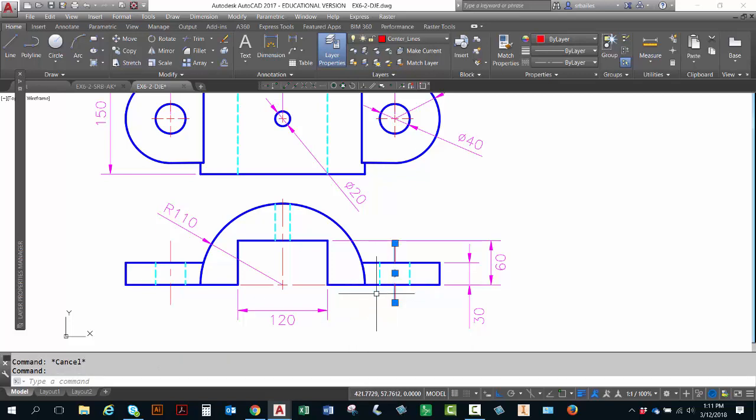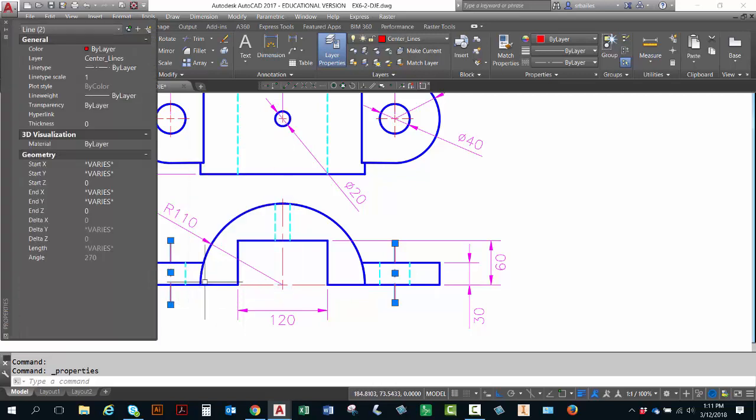Alright. Let's just try that. We'll pick both of them and right click, Properties, and we'll go to Line Type Scale, and this is for individual right here, not global. LTS in the Line Type Scale setting by typing LTS is global. This is individual. I want this to be just a little bit smaller, so I'll put 0.75, 75%.